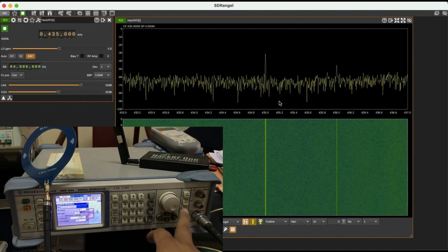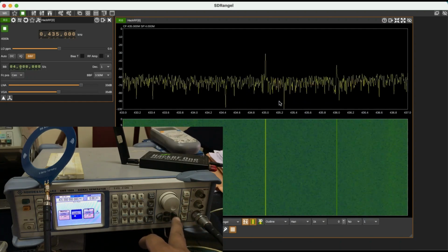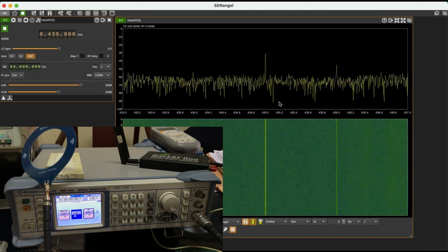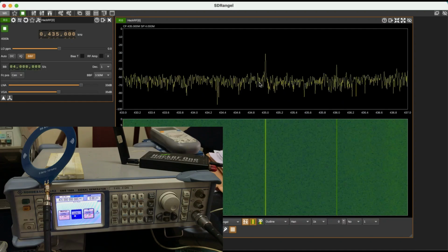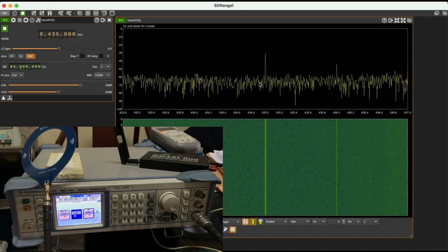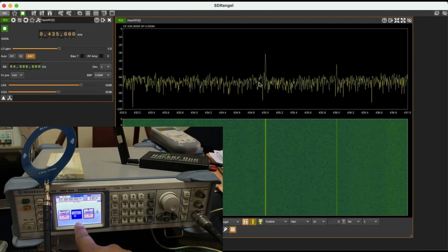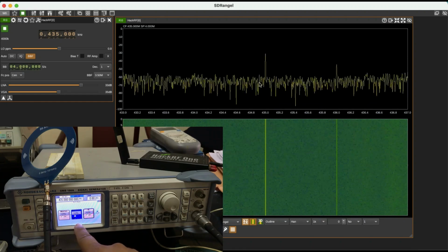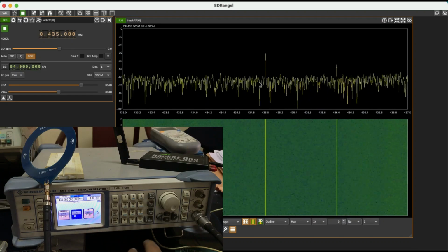So my modulation is on. I'm going to escape out of this, and nothing is being transmitted, as you can see on the spectrum. So what I'm going to do next is this. I'm going to turn on my RF, because this thing is generating a 1 megahertz signal that is going to be modulated on the 435 megahertz signal. This is how this function generator is working.